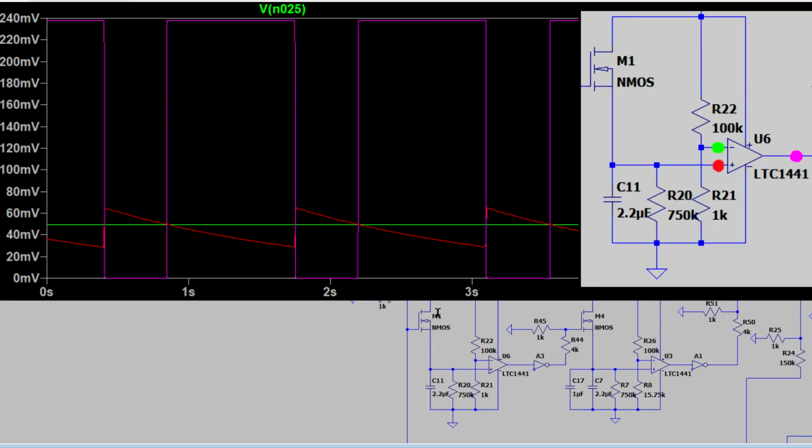The plus pin of the comparator is connected to the capacitor, and the minus pin to a voltage divider that creates constant voltage. The comparator changes its output when these voltage functions intersect. Here we can see how the comparator's output depends on both voltages. The first charging curve of the capacitor determines the phase shift of the signal.